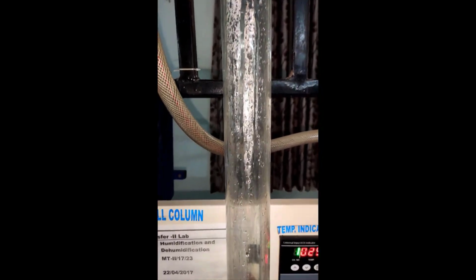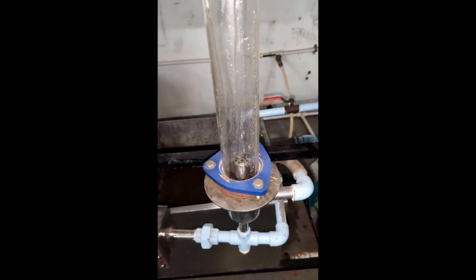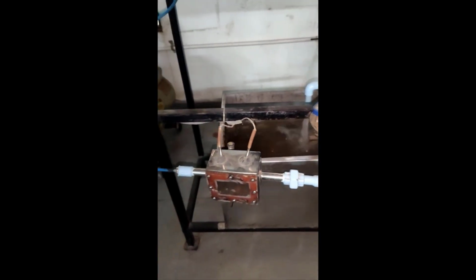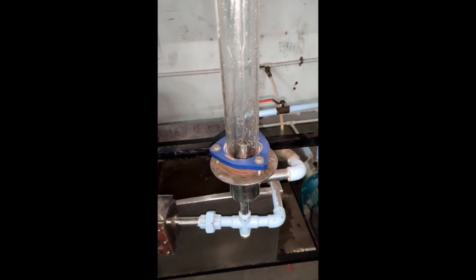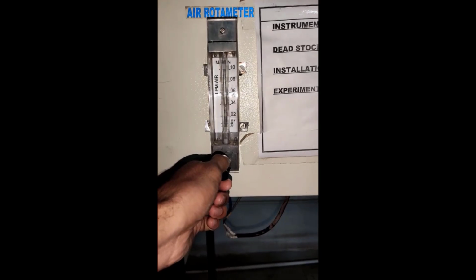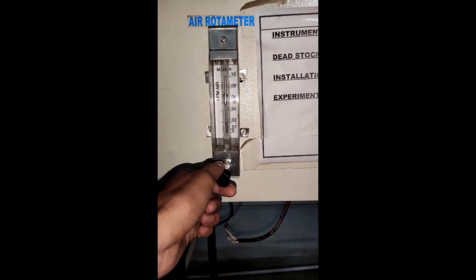Okay, and along the boundary of this column, you can see there is a little bit of humidity, or you can say humid air, because of this heated air, and this is a thermocouple. Okay, so from this we can find out the inlet and outlet wet bulb and dry bulb temperature. This is a water rotameter, so again we have adjusted the flow of water, and now we will start adjusting the air flow rates. As you can see, in this manner we can adjust the flow rate of air.